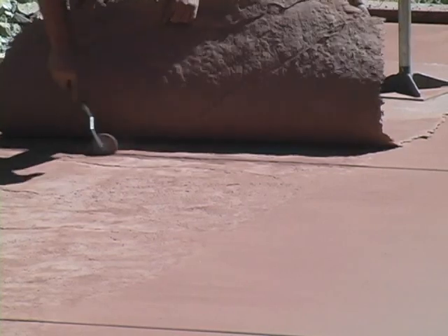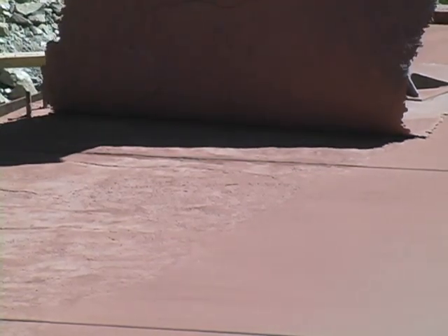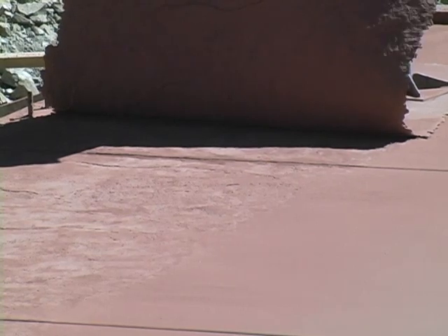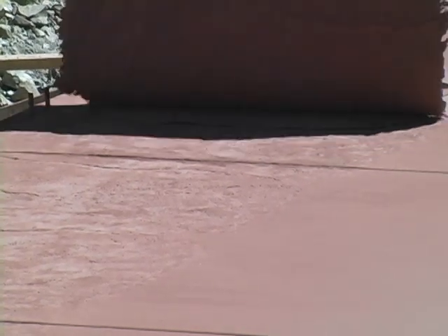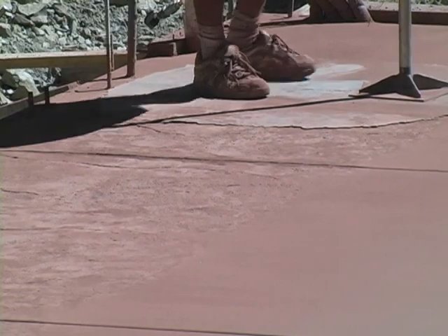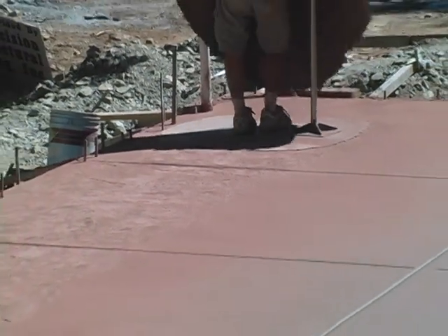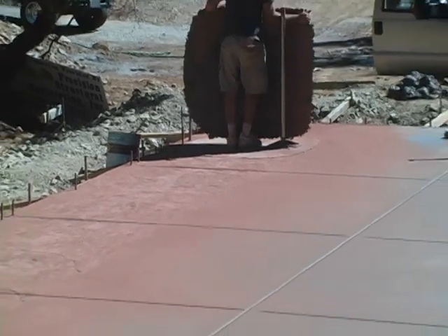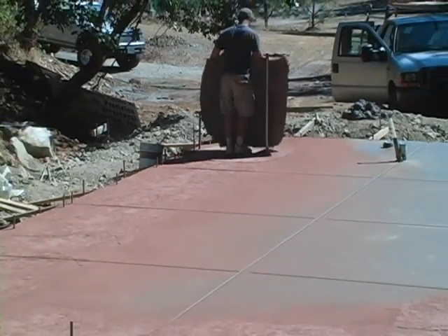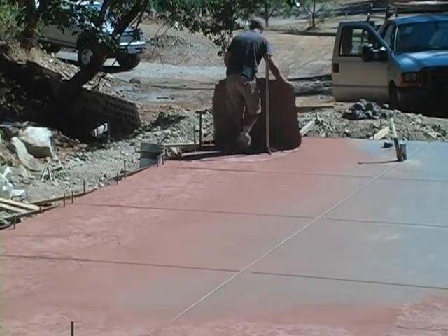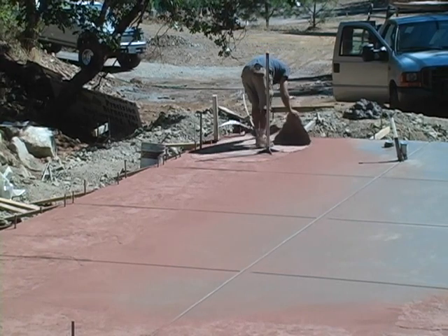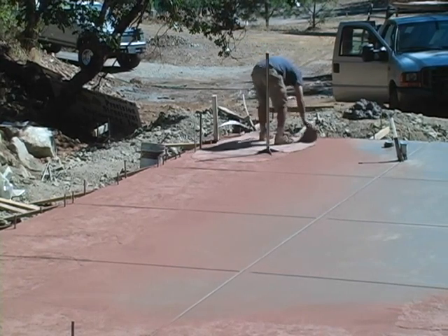And when you go over the grooves that we'd cut earlier, we want to make sure to use our wheel to clean those out so we don't have lots of color sitting in them. If we have too much color sitting down in those grooves, it shows up as a fairly obvious color change in the final product. And you can see here as he turns around, he's not only turning the stamp from one direction to the other, but he also rotated it 90 degrees. Again, laying it down and then going back and stamping over the top of it.